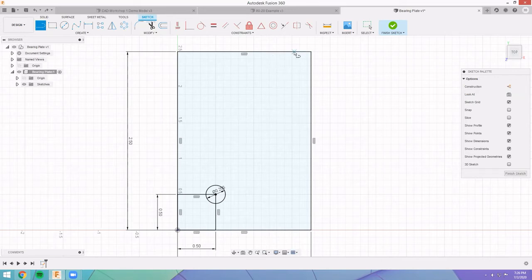So what we can do is if we come up onto this line and we slide over to the middle, you'll see that change right here. And you'll notice that my cursor is sort of like clinging to that point. So we still have that X for coincident. So the first point of our line is still going to try to be on this top line. And that triangle basically means midpoint. So when I click this here, that first point is always, always, always going to be in the dead center, intersecting this top line.